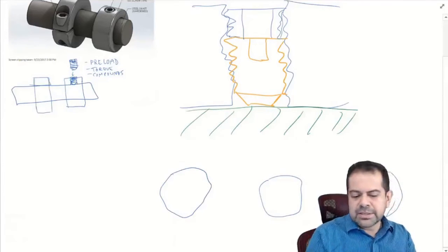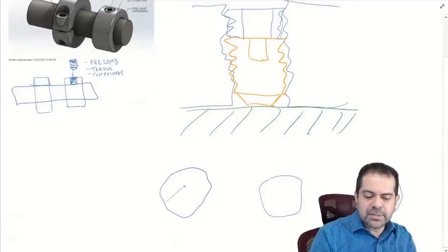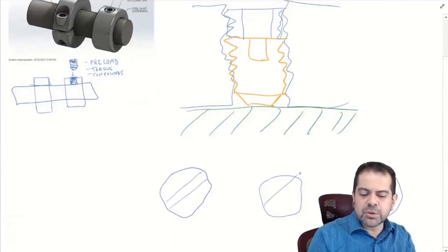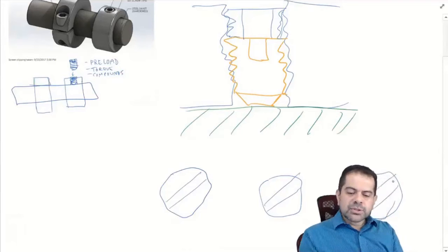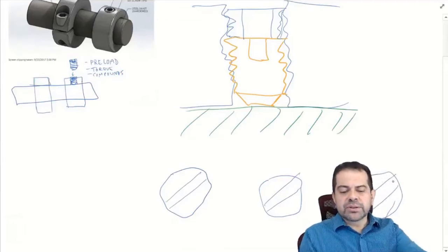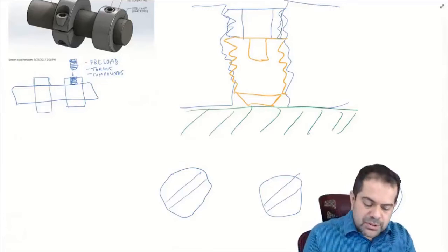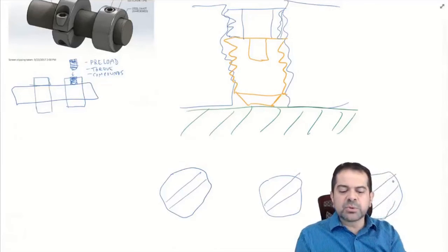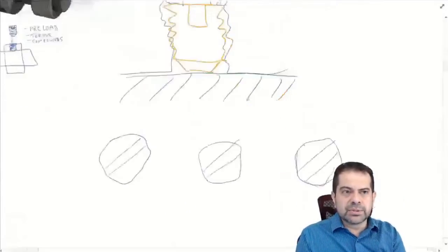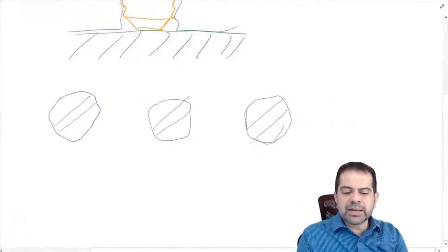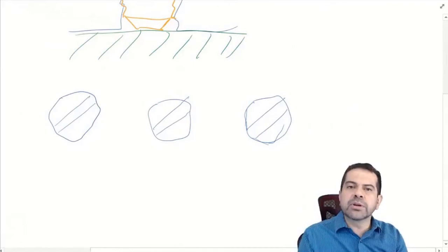Okay. In this case, we have 3 in a row, and as I mentioned, that approach has holes going through the head. So you can route this wire through these heads, all of them at the same time. If you do it in the proper pattern, it'll keep them from backing out. So in this case, if we want to back out, we're looking at a top view. If we want to back out,